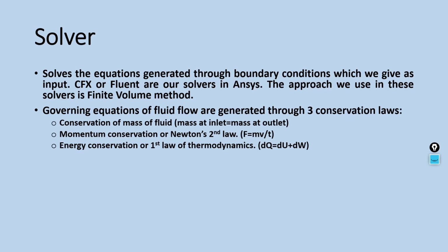Now let's discuss a few things about equations in solver. The simple thing we should know is that the governing equations of fluid flow which the solver solves are generated through three conservation laws. The laws are conservation of mass of fluid, which is mass at inlet is equal to mass at outlet. The next law is momentum conservation or Newton's second law. It says that force is equal to the rate of change of momentum. And the last one is energy conservation or first law of thermodynamics, which says that the rate of change of energy is equal to the sum of rate of heat addition to the fluid and rate of work done on the fluid.